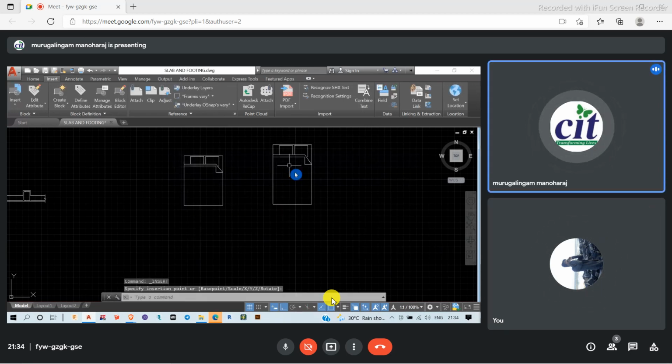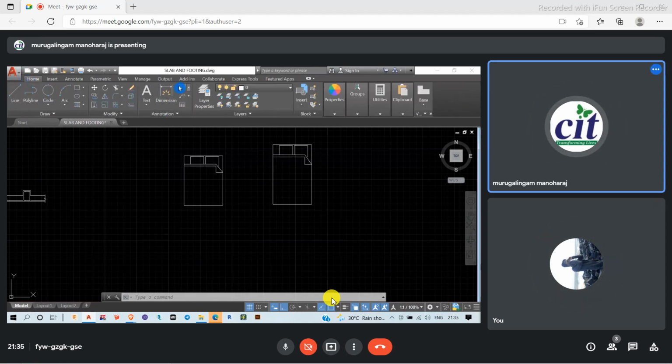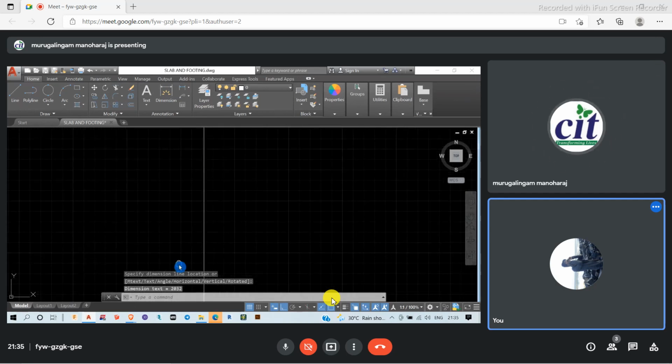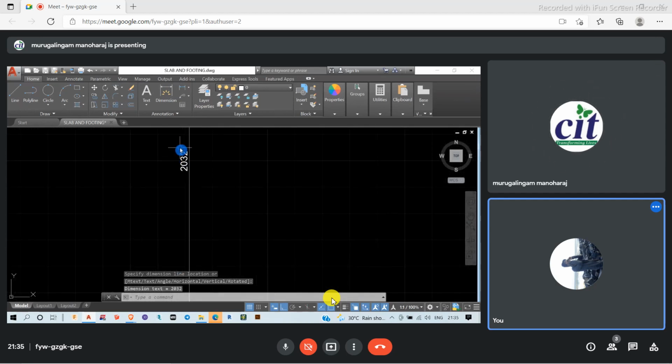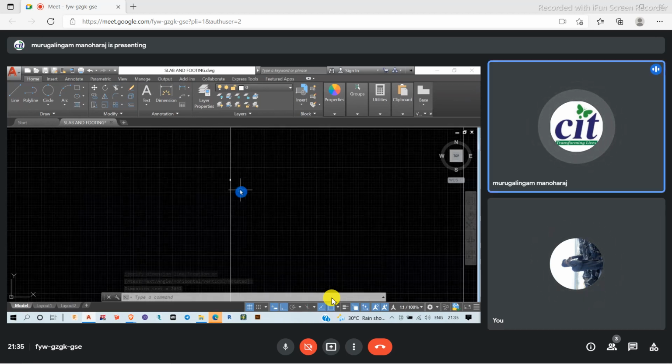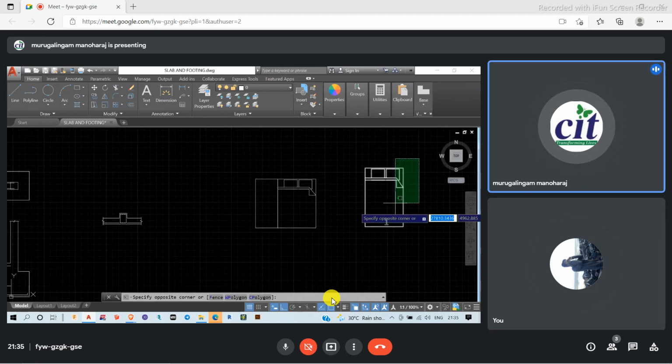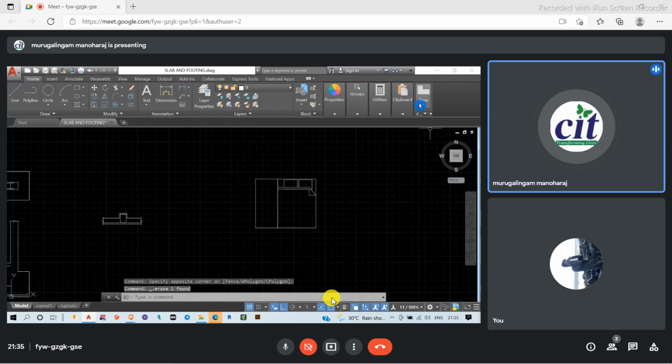So my x direction is going to look the same, but in the y direction it will be a different dimension. I will show you how to put the correct values here. For example, just measure the dimension here. The dimension I measured is 2032, and I want this width to be something like 2500. So what I have to do is open my calculator.